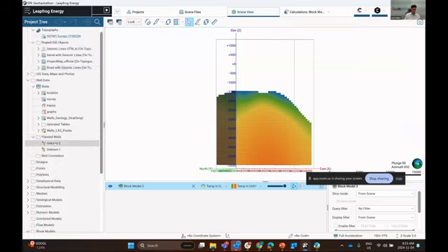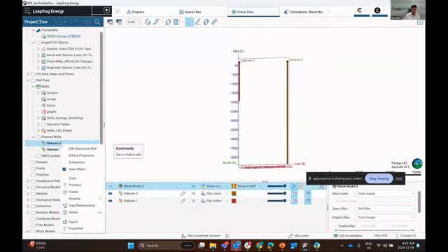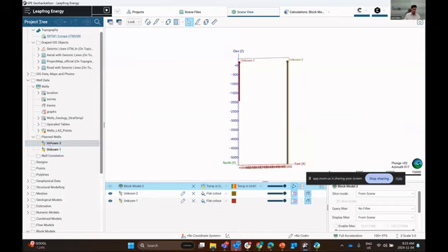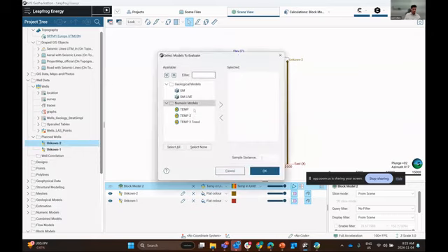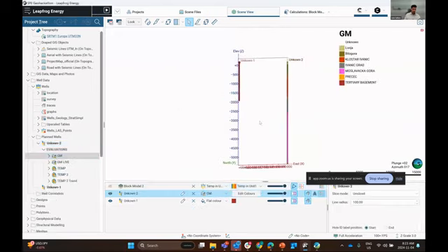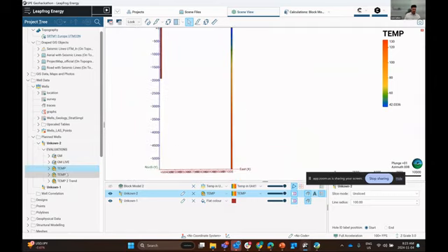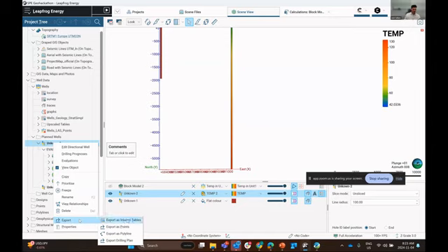And finally, the planned wells that we looked at before, the objects that we created in 3 dimensions can be evaluated onto these planned wells, which are the locations of your unknown wells by right-clicking and pressing evaluations, and we can evaluate temperature distributions and geologic units onto these planned wells. So this unknown 2, we can see the different geologic models that we generated, also the different temperature profiles. These can be exported as interval tables or points, which can then be fed into your either machine learning algorithms or compared to your machine learning algorithms.